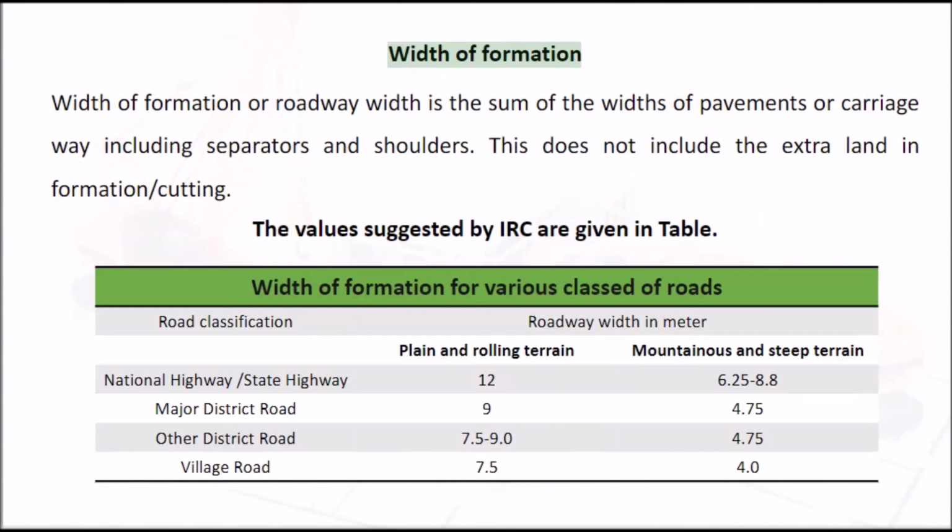Width of formation. Width of formation or roadway width is the sum of the widths of pavements or carriageway including separators and shoulders. This does not include the extra land in formation cutting. The values suggested by IRC are given in table.